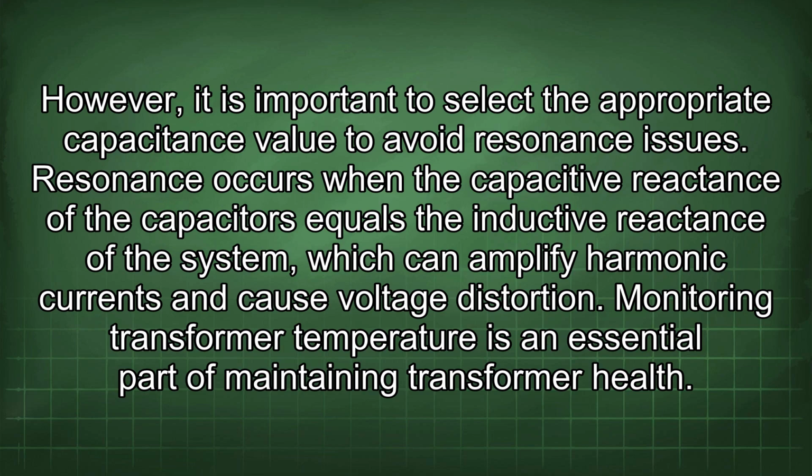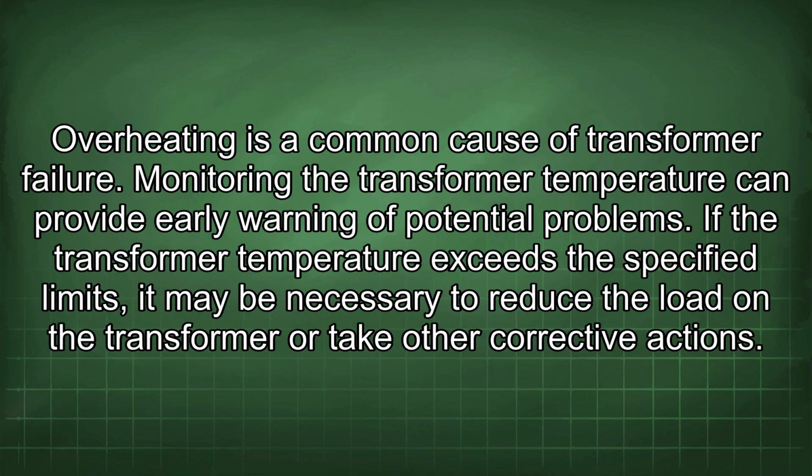Monitoring transformer temperature is an essential part of maintaining transformer health. Overheating is a common cause of transformer failure. Monitoring the transformer temperature can provide early warning of potential problems. If the transformer temperature exceeds the specified limits, it may be necessary to reduce the load on the transformer or take other corrective actions.